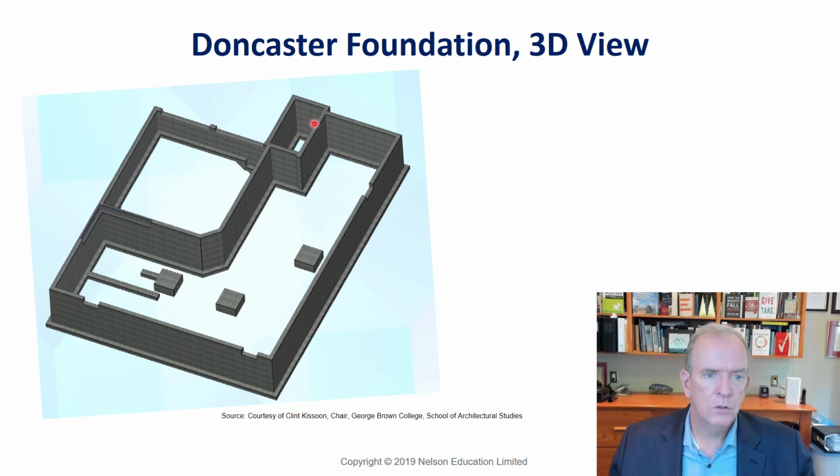Now, using a 3D model to look at this, you can kind of see right off, you've got footings, you've got column footings here, you've got a strip footing to support the wall, you got another little column footing with a strip here, and these two are supporting, see the little cutout there for the floor joists above, that's going to be supporting that sunken laundry area that's above it. This is the garage. You can see that the garage is stepped because there's no basement, but the footings of the garage are not as deep as the rest.